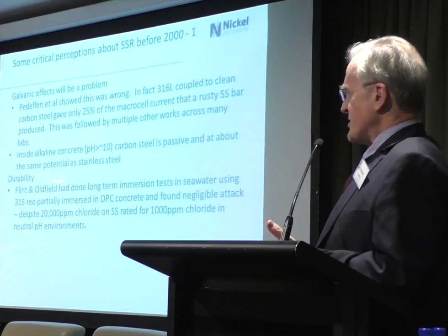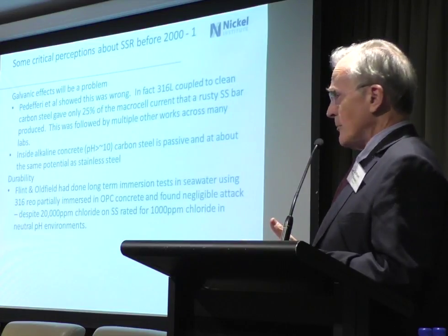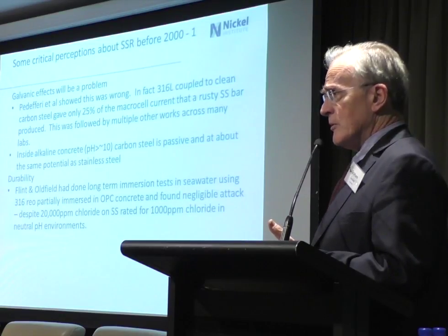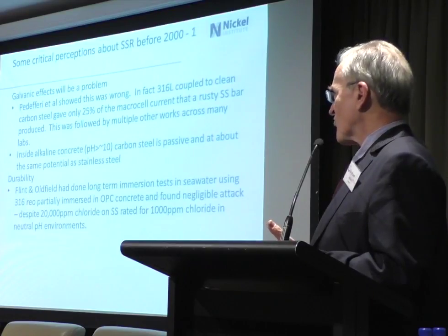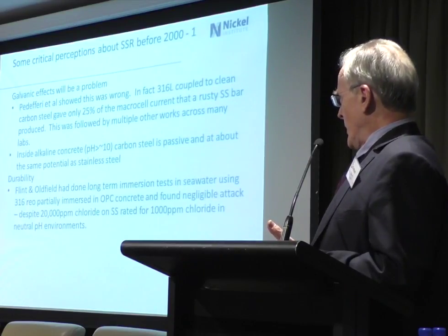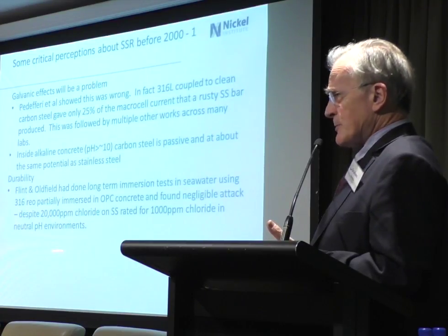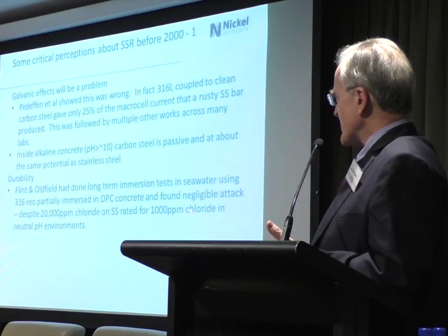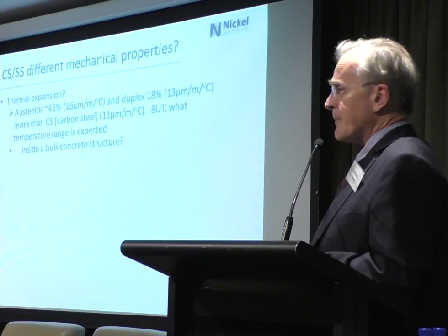Durability, this stuff that I talked about, done by the Building Research Establishment in the UK, and basically showing that 316 in seawater would be okay if it was connected to concrete. Fine. I'll show you a slide in a minute, but we're talking 20,000 parts per million chloride in seawater. The typical 316 number in neutral environments is about 1,000 parts per million.